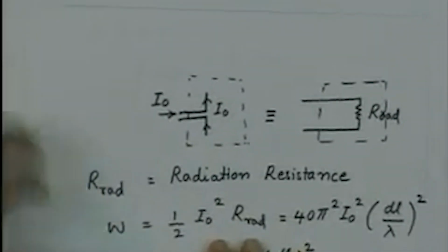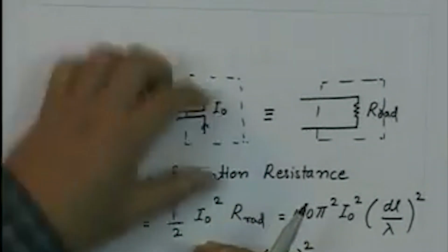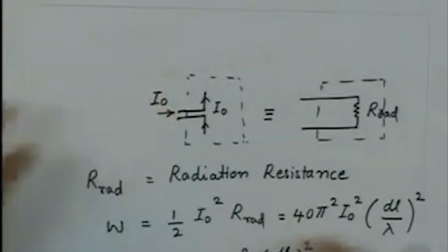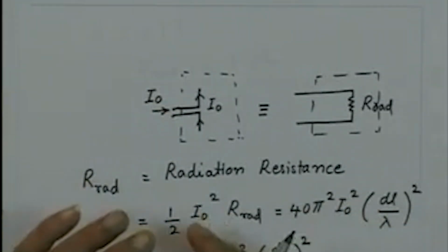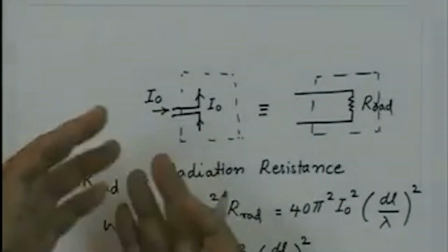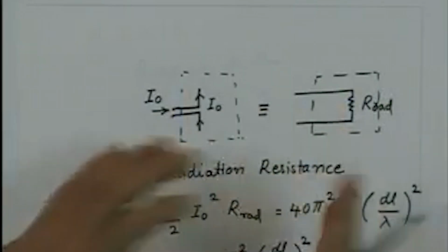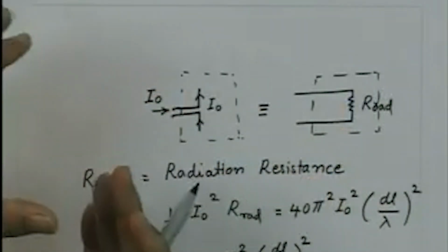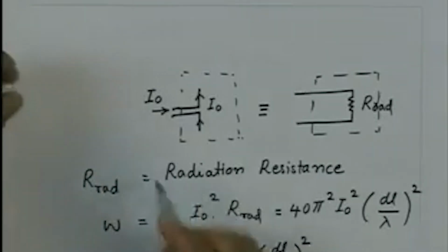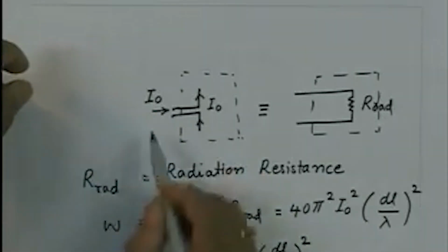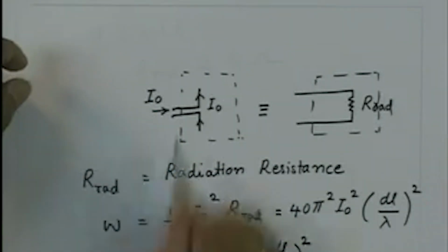Firstly, if I want to excite this structure, I will be using some transmission line for connecting it, and we have seen that coaxial structures have characteristic impedances of the order of 50 ohms. If I take a parallel wire line for connecting this, then the characteristic impedance will be a few hundred ohms. So practically this load appears almost like a short circuit compared to the characteristic impedances. So you have a great mismatching problem between the transmission line and the antenna when you try to excite it.